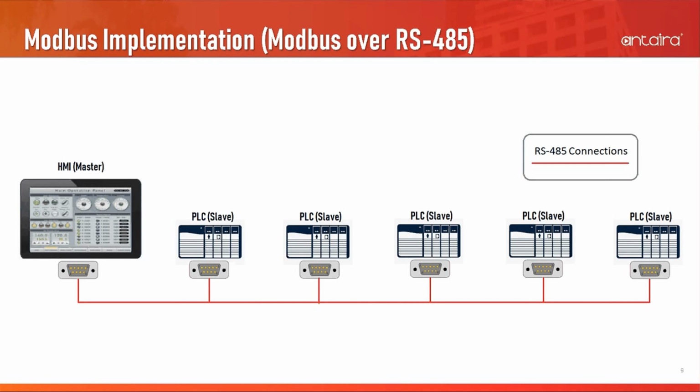However, the Modbus communication protocol uses half duplex communications, since Modbus operates in a master and slave paradigm, in which only a master can initiate the request, then the slave will process the request and return some information back to the master.